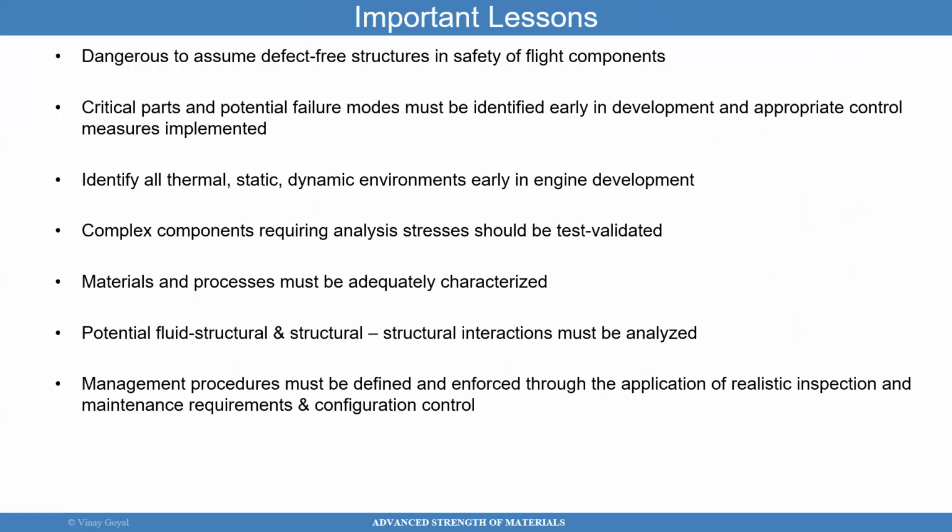Important lessons to keep in mind is dangerous to assume that structures are defect-free. Critical parts and potential faults should be identified early in the process. You want to identify all the environments well. Like if you're going to see a part that's going to experience temperatures and environments, it's going to experience loads. You want to get those loads right, right?